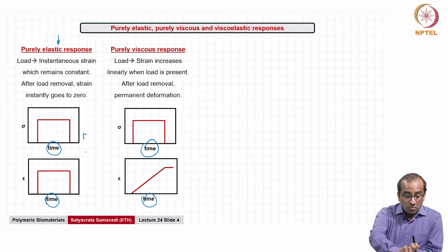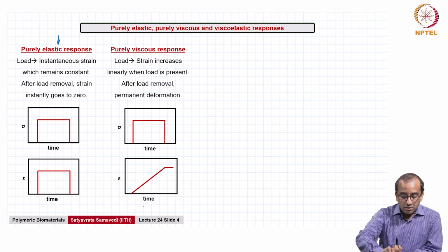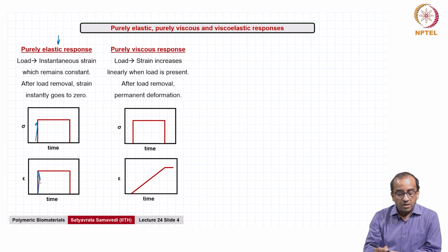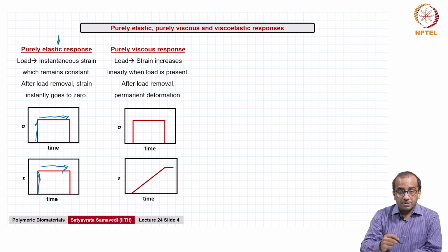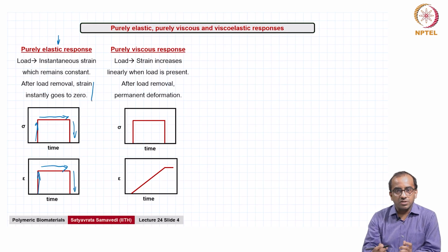So here what we are looking at is as soon as the load is applied, there is a deformation, and as long as the load persists, the deformation persists at a constant value, and as soon as the load is removed, the material goes back to its original position. Strain instantly goes to 0. That is the purely elastic response.